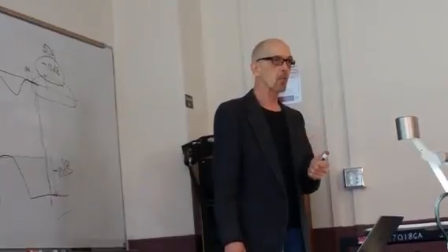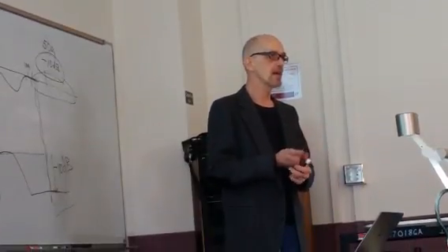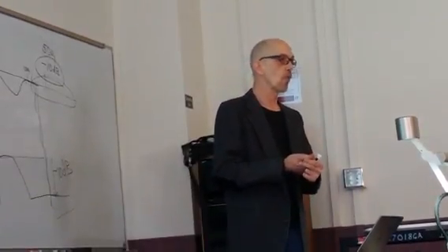You've had homeworks on that, and it's discussed in the book. When you've got a type 1 closed loop system, it is type 1, isn't it? Does everybody see the type number? Because we didn't get rid of that 1 over S. We got rid of the 1 over S plus 1, because the controller has an S plus 1 in the numerator. So that goes away, but the 1 over S is still there. So the closed loop will still be type 1. It'll still have finite non-zero steady state error for a ramp.